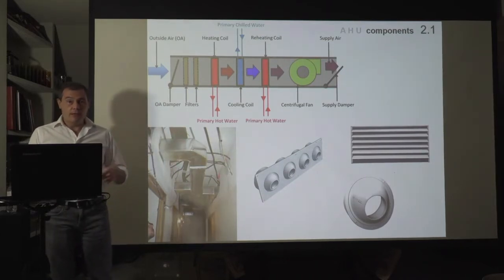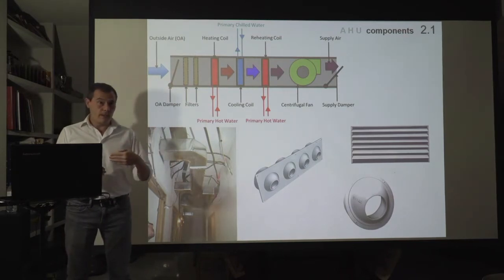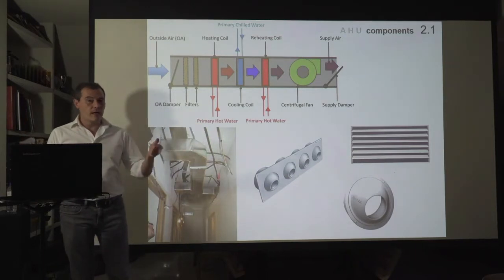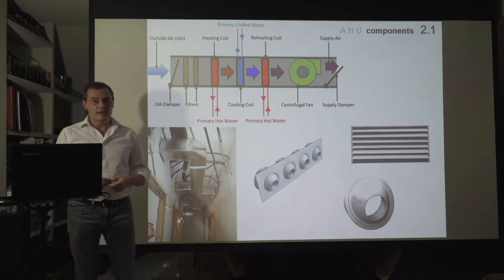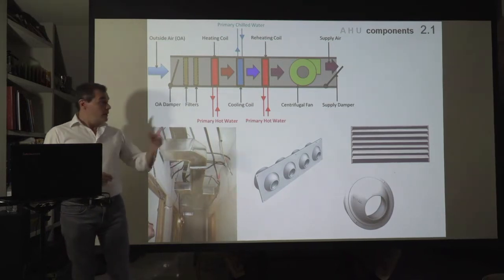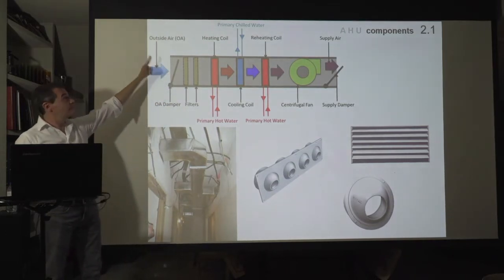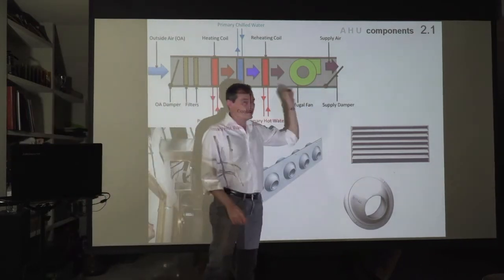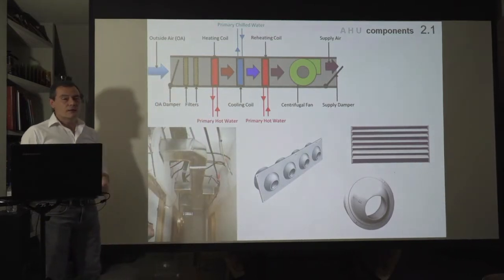It's almost empty, and it has a few things that make airflow. And as the air is flowing through that device, through that box, we can heat up, we can cool down, or we can add or remove water or moisture from the air. So this is an air handling unit. We have an air intake for outside air, and we have an air outtake. So we supply that air, that fresh air, to the interior.